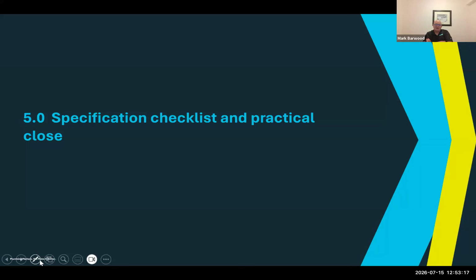go up to 150. Just depending on designs, the way recircs work, there can be a net heat gain because if a building isn't well piped or the mixing valve's failing, on a recirc return in a mechanical room, you're going to send back a percentage of the water back to the heating source if the water's too cold, and if the water's too hot, you're going to send 100% of it back into the recirc. So if you keep recircing pipe and it's a closed loop because no water's getting used, eventually that water will cool down because there's no way to reintroduce more hot water into that line. It's become a closed loop overnight.